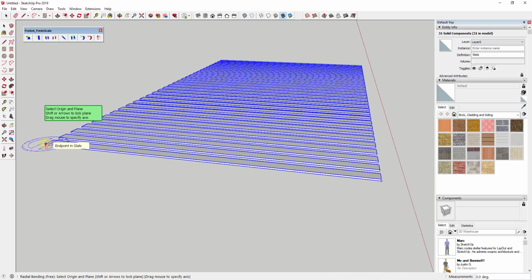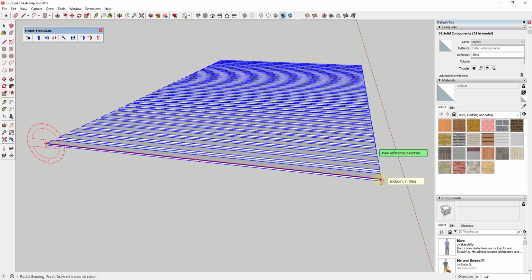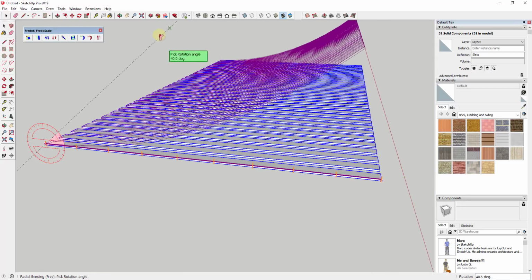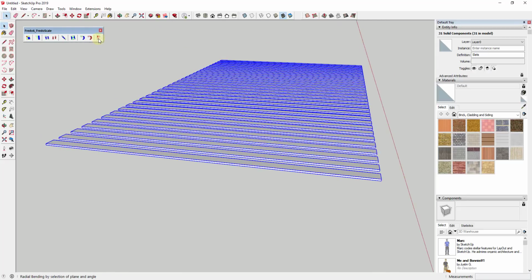And you've seen what we've done before, where we've taken Radial Bend and bent a whole object like this, so bending the whole thing. Well, what I want to do here is, instead of bending the whole thing, bend this starting at maybe like this point right here, and bend this section in between here.